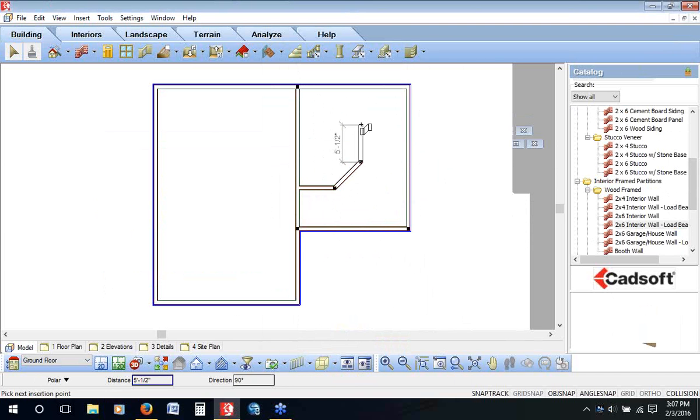and I'll go up 5 feet, hit enter, but now I want an oddball angle. That's where I would turn off angle snap as well. And now look, I can go at any odd angle that there is. My direction there can go to anything that I want it to go to. So I can pull down in any odd angle. Okay, so if you want to have ortho on, that means I'm restricted to straight up and down 90-degree intersections. Angle snap will restrict me to 15. Turning both of them off will allow me to go to any angle.